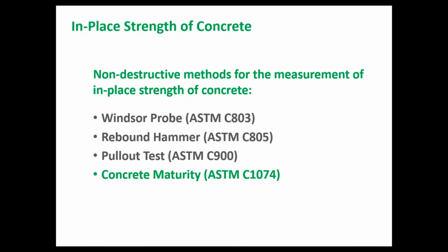Okay, what are the options and alternatives instead of break test? Well, over the past decades, standard bodies and committees and researchers have developed different test methods to accurately capture strength hardening in concrete and not rely solely on break tests. So there are different non-destructive test methods that I've listed here. All of them are standardized by ASTM. And so the first one is Windsor probe, where you would basically fire a probe in the concrete, and the penetration depth of that probe or rod is correlated with concrete strength.